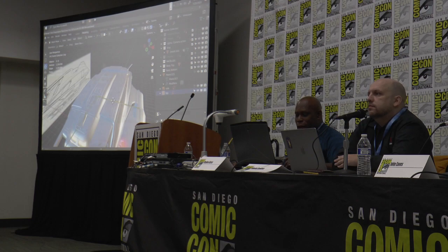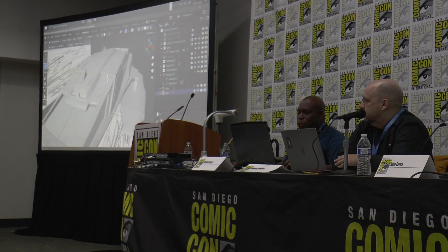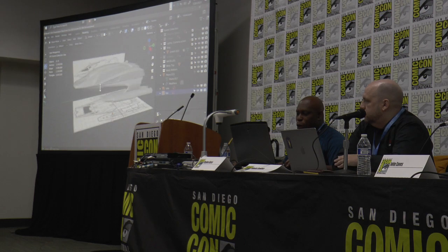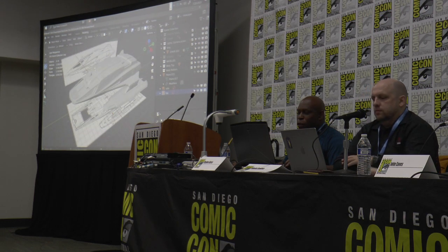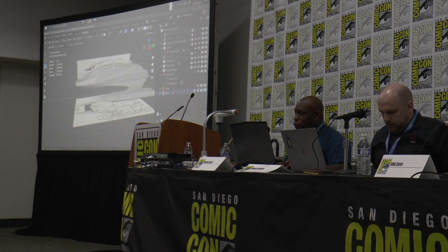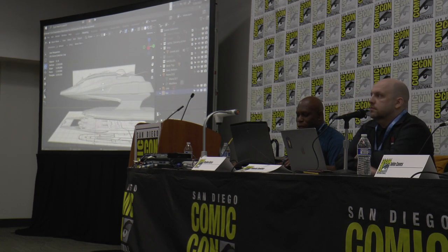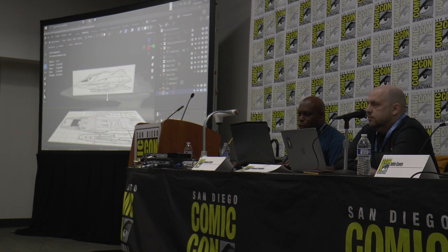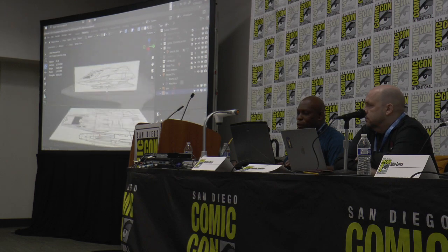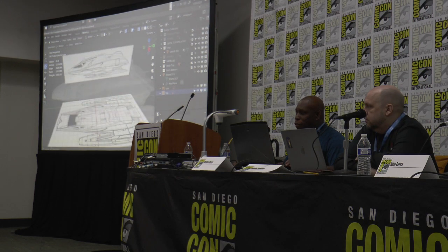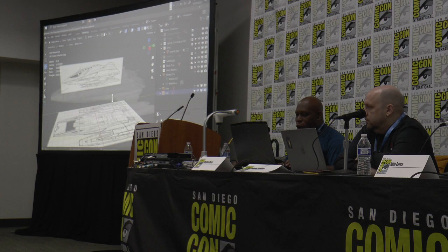So let's get out of here. Z key, hold it down, go to my solid view, and let's start breaking this down and show you my workflow here. A top view, a side view of my ship, just as a reference, right? If I want an X-ray view of the model, hit the Alt or Option Z key, goes to X-ray view so I can see through my model to my images behind it. That's a nice little workflow. Alt or Option Z again to bring it back to standard shading view.